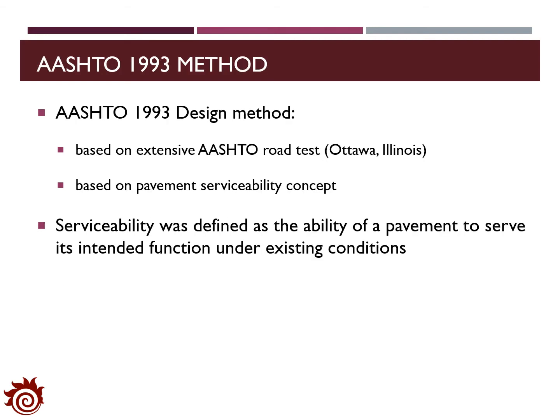Currently, most of the existing pavement design methods are based on the AASHTO 1993 method. This method was designed based on the extensive AASHTO road test conducted in Ottawa, Illinois, and it utilizes the pavement serviceability for the design. Here, serviceability is defined as the ability of the pavement to serve its intended function under the existing conditions.